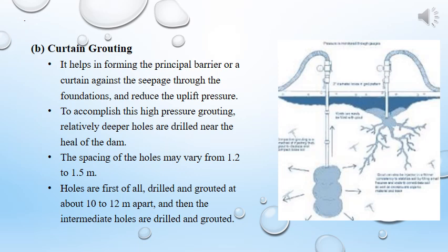To safeguard against uplift, we provide foundation grouting, that is, consolidation grouting and curtain grouting. Consolidation grouting was already discussed in previous presentations. Curtain grouting helps in forming a curtain against the seepage through the foundation and thus reduces the uplift pressure. For this, relatively deeper holes are drilled near the heel of the dam.